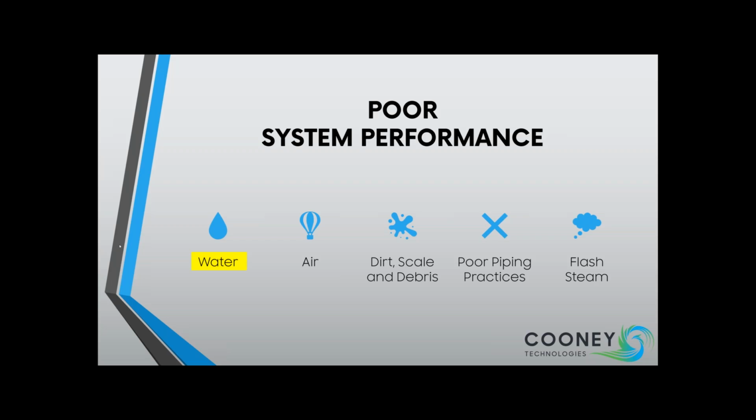And come to think of it, speaking of problems, one problem I just encountered recently was a poorly insulated steam main that fed a bank of steam preheat coils in the basement of a Philadelphia school building. In fact, there was no insulation on this 3-inch steam main. The steam main ran exposed through about 20 feet of an outside air plenum in the ceiling on a 15-degree day before dropping down into the bank of the vertical steam coils.